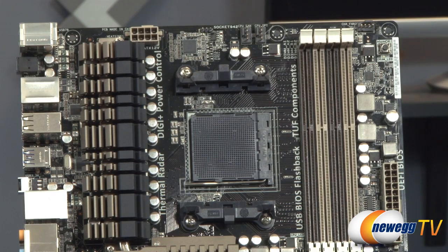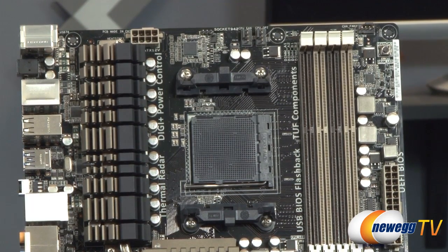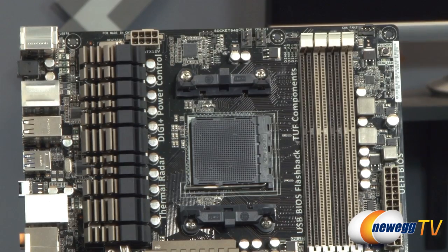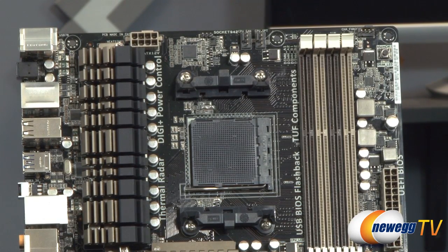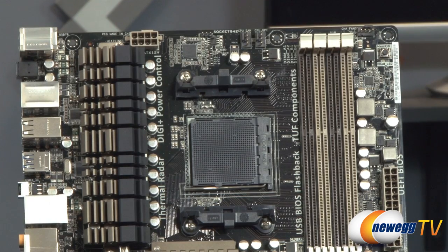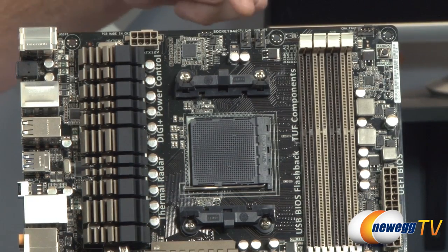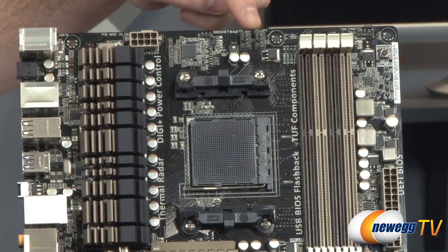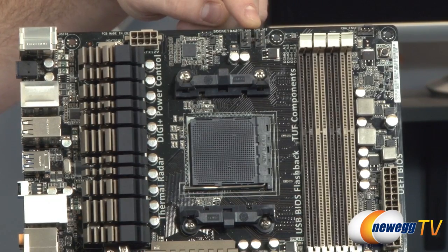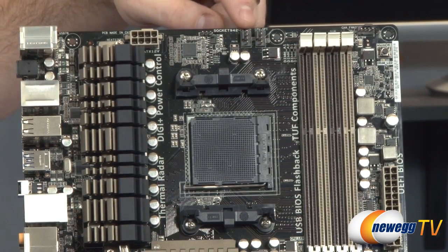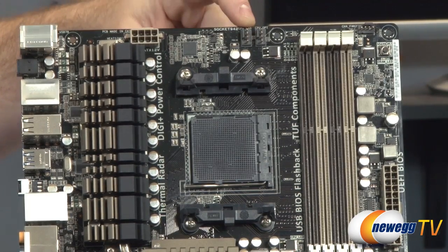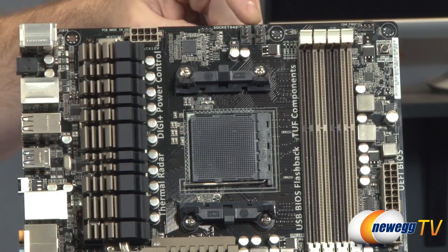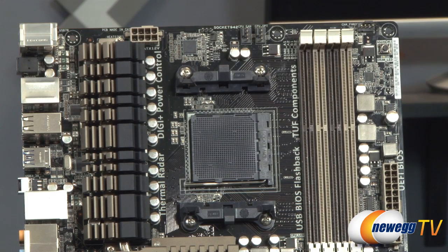Fan connectors. We actually have not mentioned those yet at this point, but I always recommend, if you have the option, to plug your case fans directly into your motherboard. That will give you some additional control over them. On this board, for example, you can see some 4-pin fan connectors up here at the top. There's also 3-pin fan connectors, but the 4-pin fan connectors will give you PWM, or pulse width modulation control, which I find to be a superior method than voltage control. But you also see 3-pin fan connectors that give voltage control as well.